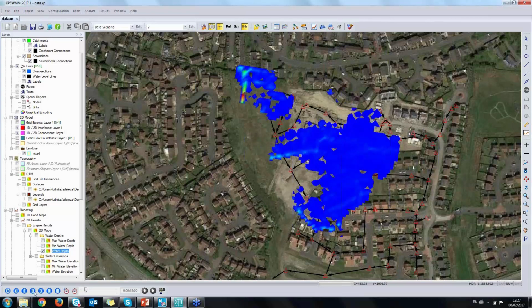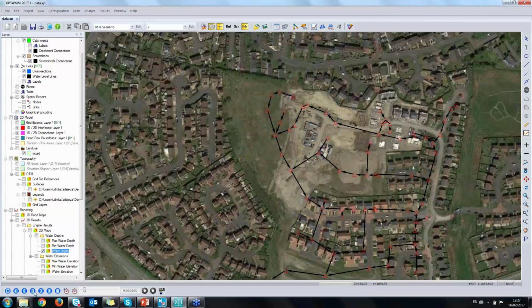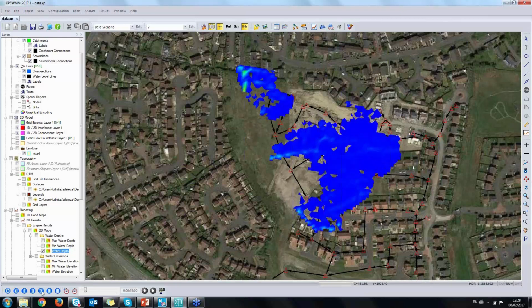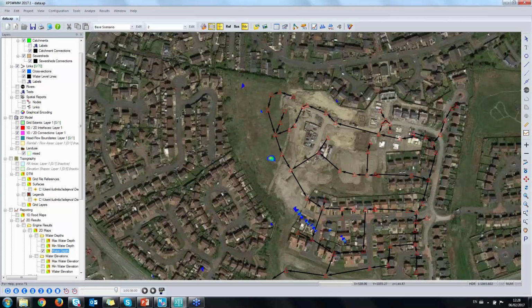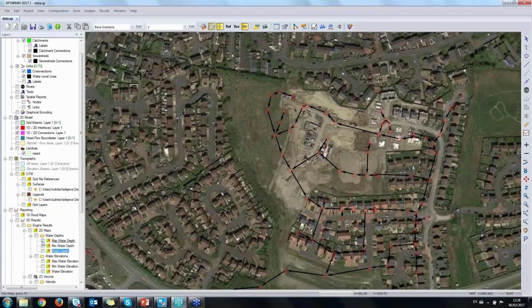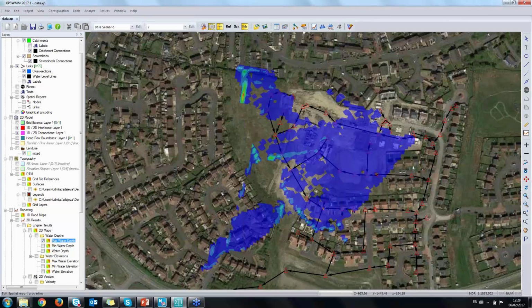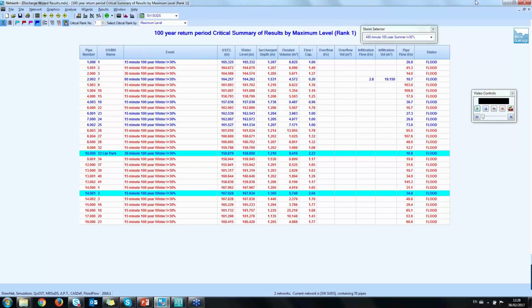So if I go a bit back, perhaps pause it, we can see that there are some manholes quite upstream of our networks which are flooding, right? So obviously maps show some type of results, which we love to see. But which manholes are flooded, we can easily see in the MicroDrainage model. If we go back in here, we can easily see which pipes and manholes are flooded.